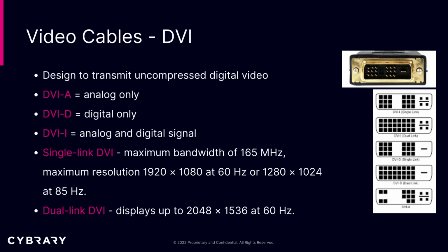DVI. DVI is a Digital Visual Interface developed by the Digital Display Working Group, or the DDWG. Now, this was designed to transmit uncompressed digital video and can be configured to support multiple modes: DVI-A, which is analog, or DVI-D, digital, or DVI-I, digital and analog.